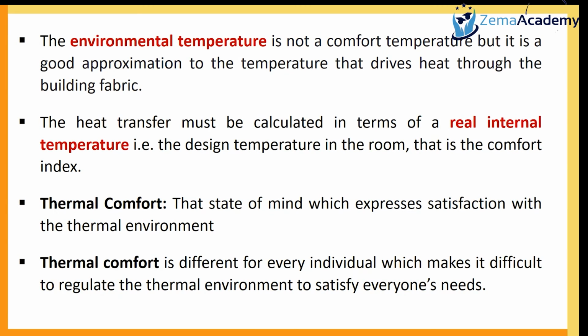And hence, when we look at this model, we say that this environmental temperature is not a comfort temperature, though this gives us a very good approximation, as you have seen when we did activity 1, we got similar values. Because this temperature is not real, we cannot use it as a comfort temperature, because it cannot be measured. It is a temperature that resulted from the manipulation of the heat transfer equation.